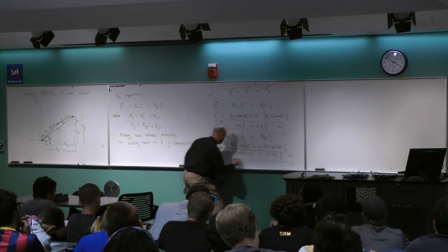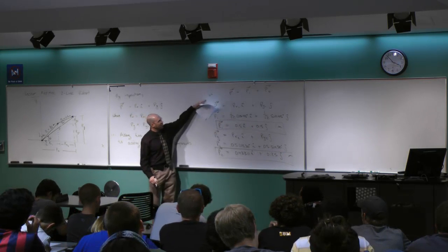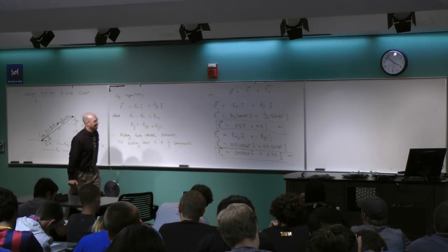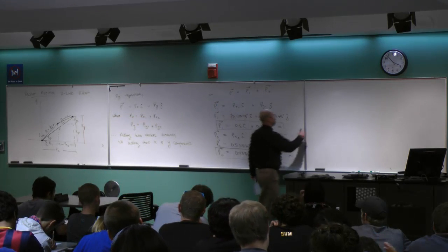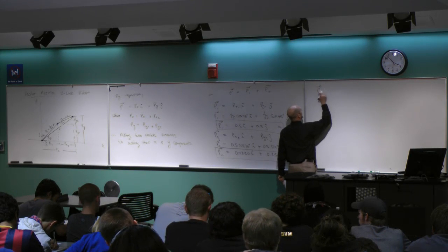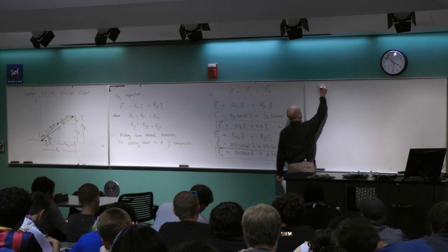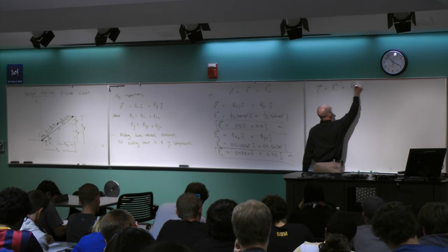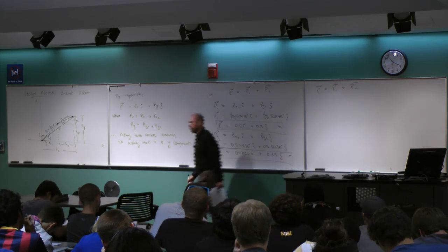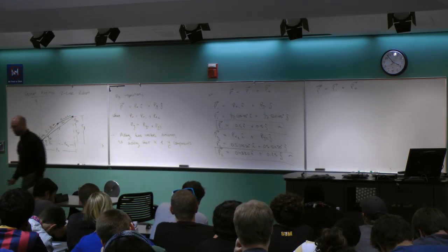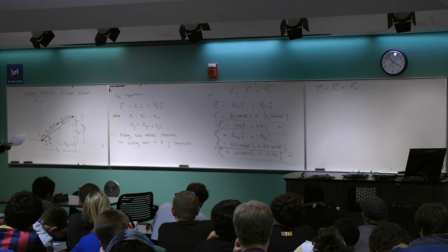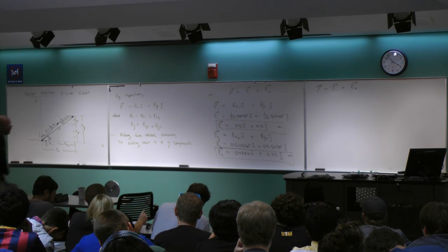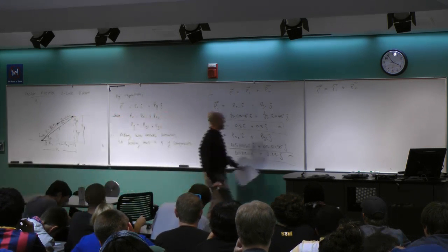Okay, so we've got the two of these, and what we want to do now is implement the vector addition. How do you do that? Well, P is the sum, P1 plus P2. The beauty of this is once you write down vectors in IJ notation, you turn a problem that used to be trigonometry into just straight algebra. So I just plug in the numbers and add them up.